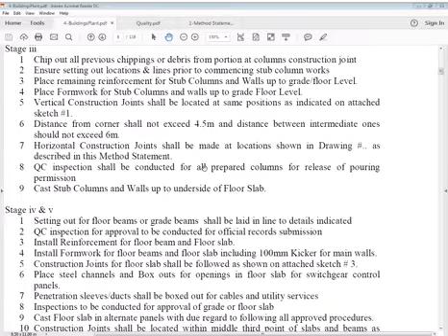Ensure setting out locations and lines prior to commencing stub column works. Stub columns, you know very well what a stub column is. This column is generally defined as a starter column part, meaning from footing it starts and goes to plinth level or ground level. That portion of small column, hardly 1 meter I think, or maybe 1.5 maximum, is called stub column, with the same section as the upper one, and maybe sometimes increased section also, because cover of concrete in foundation columns is more than cover of concrete in upper part of columns.